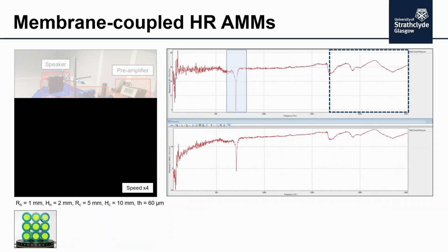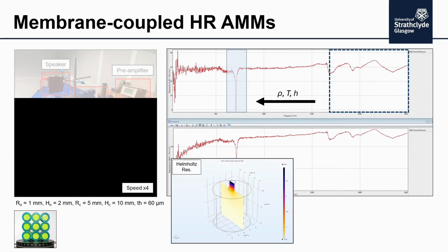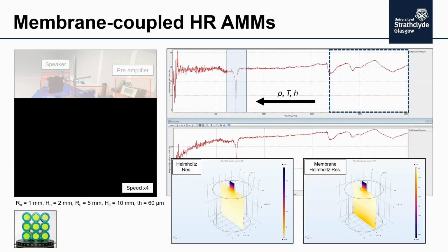We know after some investigations and some experiments that this shift mainly depends on 3 mechanical properties of the membrane, basically the density, thickness, and the tension. Most importantly, the tension. And we also know that we're moving from a 1-port acoustic system, a Helmholtz resonator where acoustic waves can only go through the neck, to a 2-port acoustic system where the membrane vibration introduces a non-negligible pressure port there, and that dictates that shift as well. So it's a combination of these mechanical properties with this 2-port system.